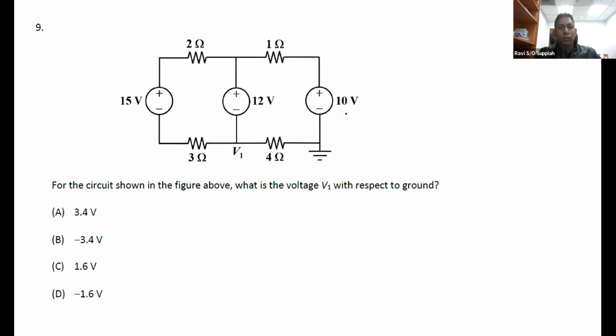All right, so the whole idea of node analysis is I must be able to define some voltages of the different nodes with respect to ground or with respect to some other voltage that I'm trying to find. And then using that, I can come up with some equation. So that's the whole idea of node analysis. If you have a different thinking and you try some other approach, and you're not able to come up with a proper equation, then you know that approach was wrong. Step back and try to take a different approach.